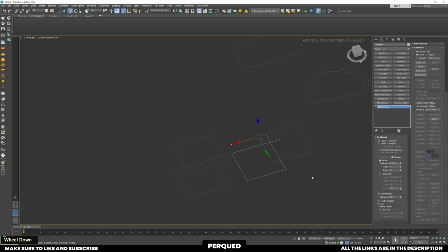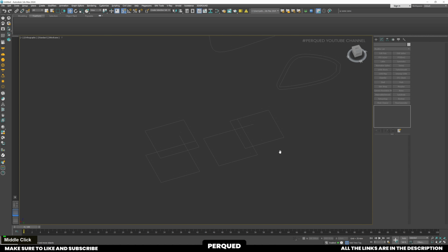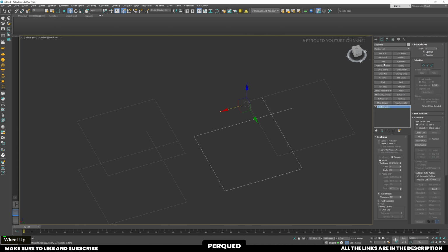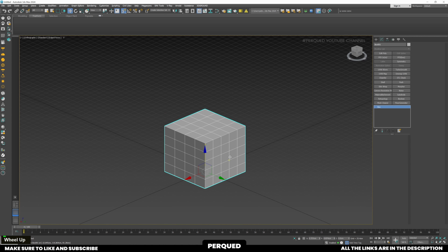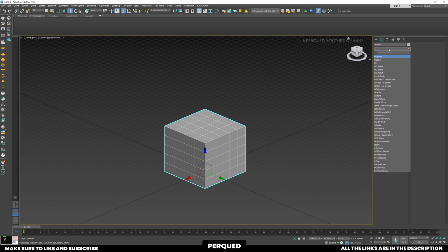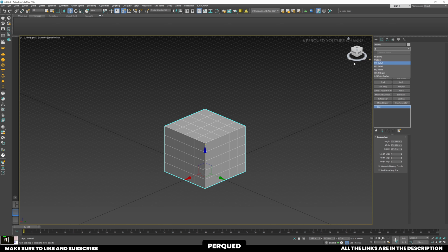Now finally, our editable spline is also over. And now we are going to look at other useful modifiers from the Modify tab. We have the FFD modifier in multiple categories: 2x2x2, 3x3x3, 4x4x4, box and cylinder. This modifier can help you make certain shapes in your work. Let's create a box and apply FFD 2x2x2.